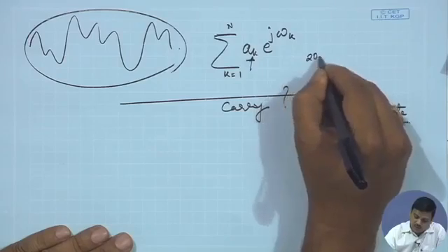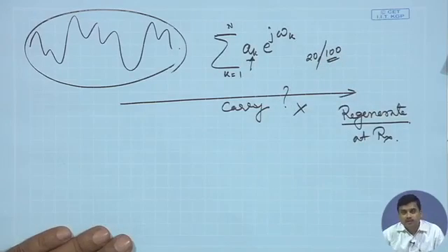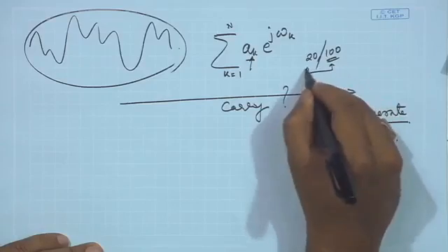So you have to predefine that the receiver knows the set of frequencies which are going to be used. If there is a certain amount of bandwidth present in the system, you say, well, I'm going to use 20 or let's say 100 different frequency components. Of course, there will be distortion, some kind of error, but if it is acceptable, then you would fix a certain number of frequency components that I'm going to use to regenerate my original voice message.